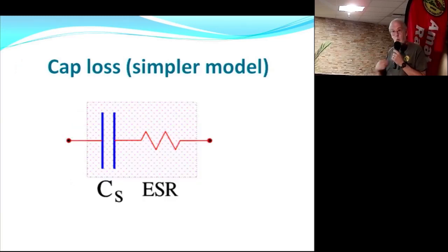Simplifying it down to where we are in amateur radio, you've got an ideal capacitor and an equivalent series resistance, ESR. And that resistor is what is going to kill what's going on in an electrolytic capacitor. You would like to have that as the lowest possible value, because think about it. If you have current flowing through that capacitor, what's that resistor going to produce inside that can or that container? Heat.